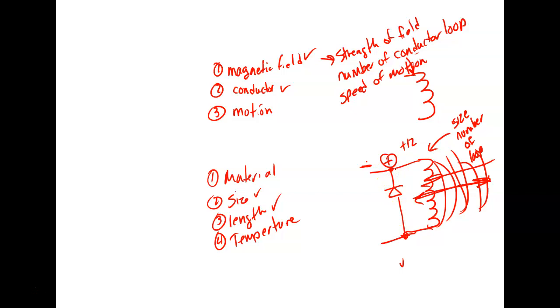Now, a diode is a check valve in electronics. A diode would only let current flow in one direction. To get it to flow, we would put the minus up here and the plus down here. When we put power on it, the minus is on the top and the plus is on the bottom, and this thing right here is a check valve. It's turned off.